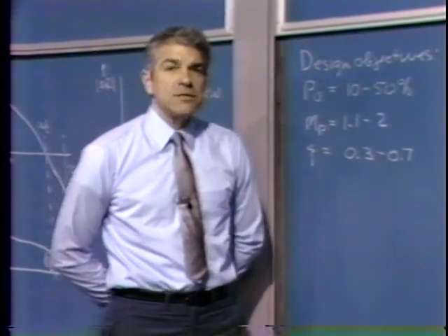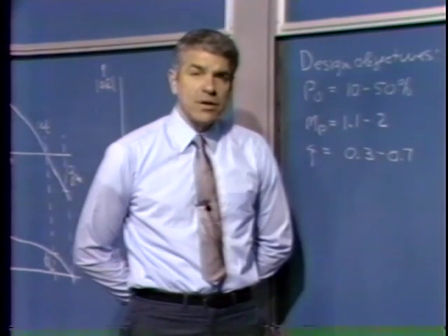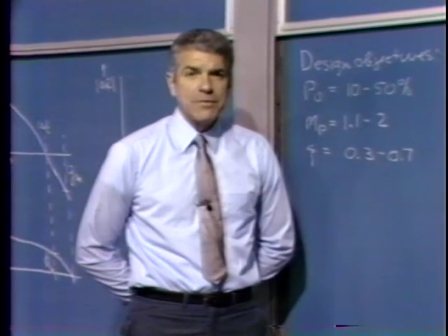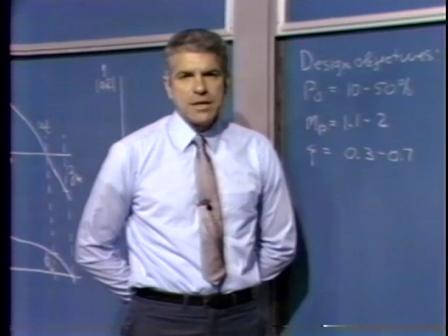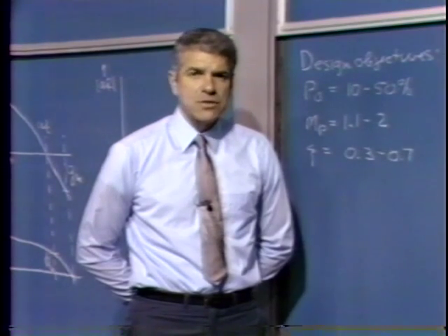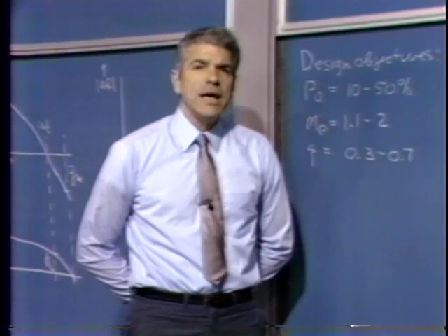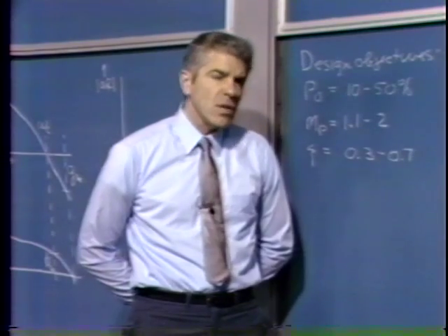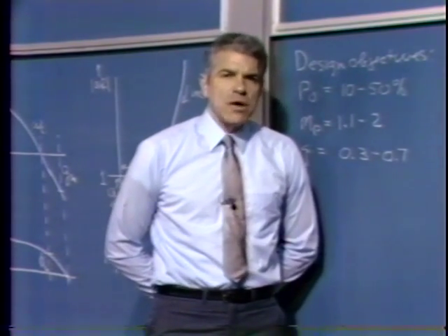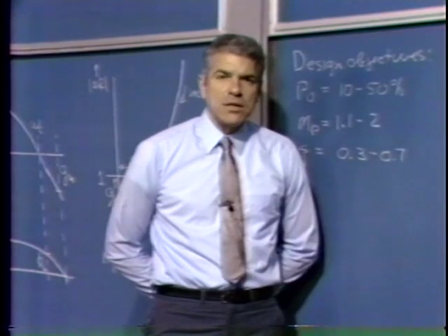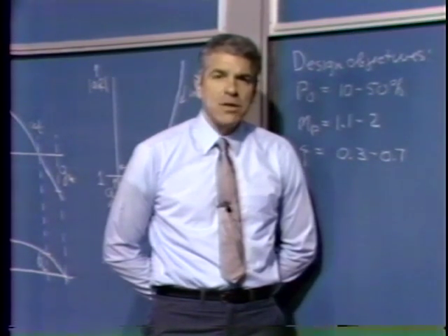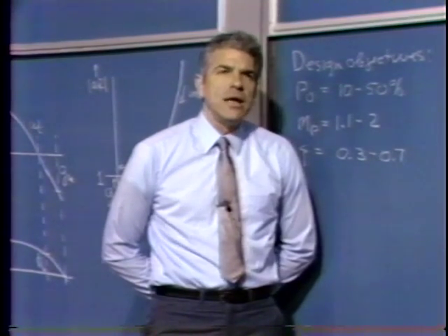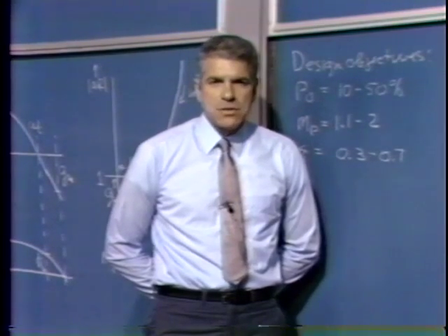But let's consider one possible modification, a very simple one, in particular changing the AF or A0 F0 product. We've already looked at that in the earlier example today when we did the Nichols chart construction, and we found out in a very direct way how changes, in that case in A0, affected MP for the system. What we assumed in doing that construction was that we were able to change A0, change the magnitude of the loop transmission, without making any change in the angle associated with the AF product. And that is realistic in some cases, but not always.